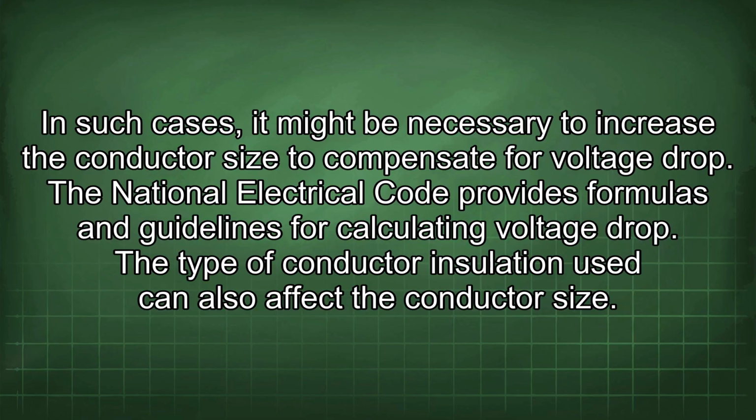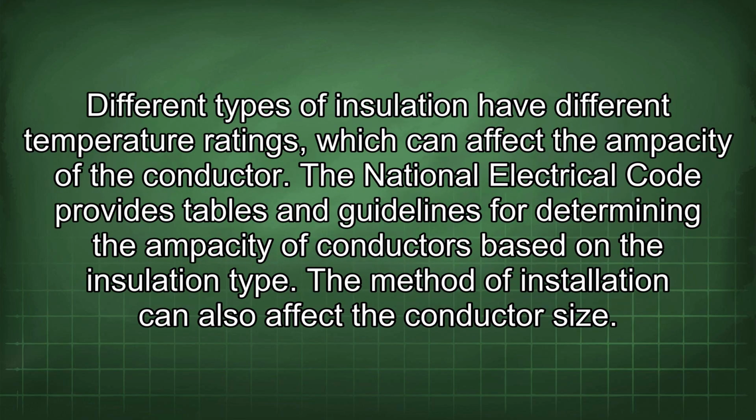The type of conductor insulation used can also affect the conductor size. Different types of insulation have different temperature ratings which can affect the ampacity of the conductor. The National Electrical Code provides tables and guidelines for determining the ampacity of conductors based on the insulation type.